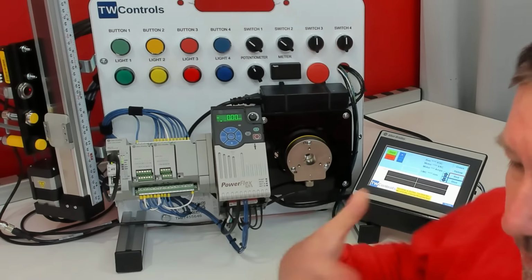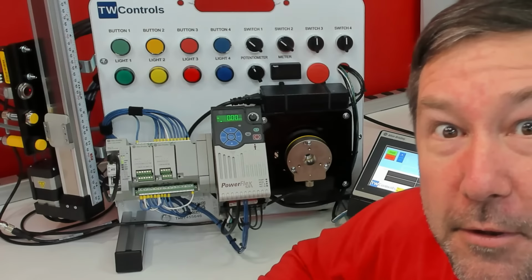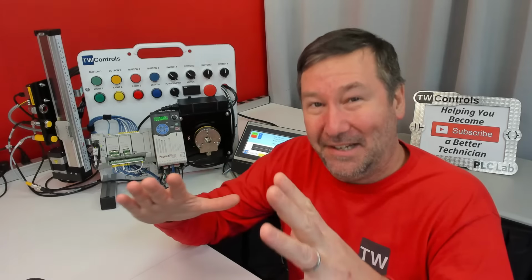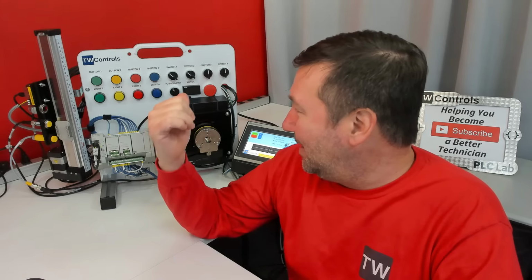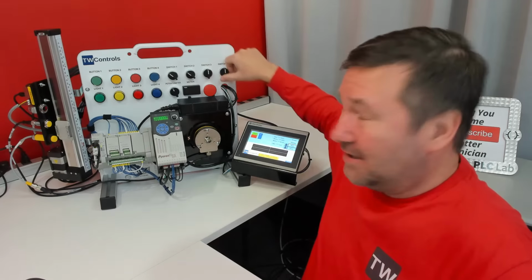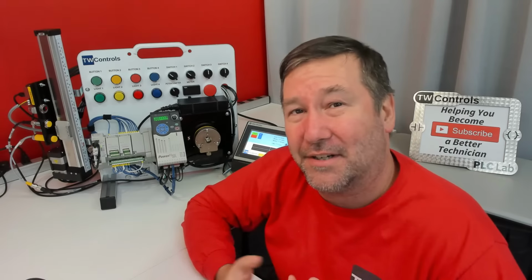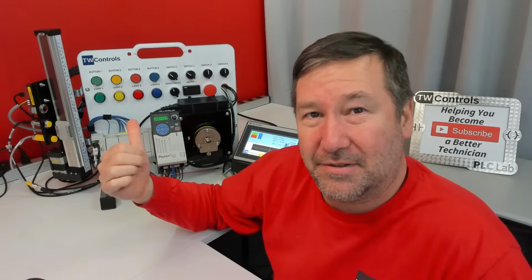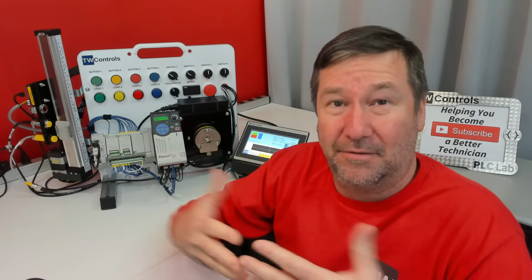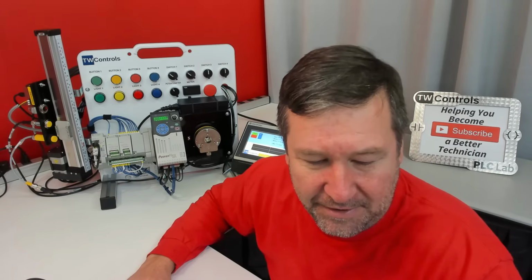And now be incredibly, as in, oh man, really big here. I forgot if I had to zoom on. Be incredibly careful because by default, the speed is 0. So if we try to start this, you may hear that little high pitched noise. I can hardly hear it. But if you run this at 0 speed, it still is applying voltage, and then you're applying heat when you apply voltage. And that fan will not cool itself if those blades are not turning.